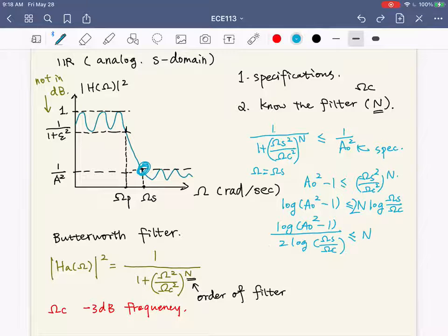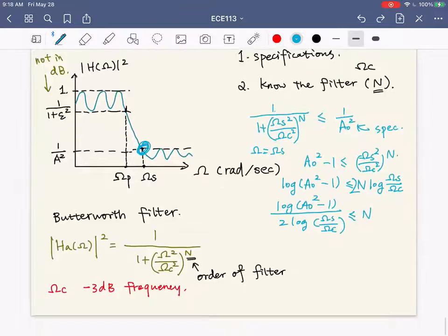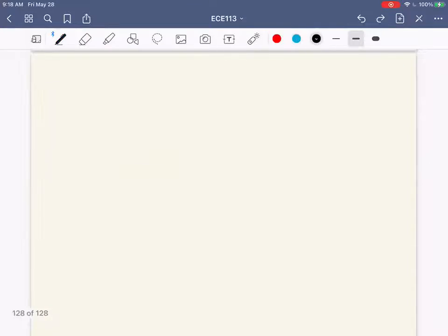So in this way, we'll be able to get our n given the other requirements. That's why we always want a bigger n if the left side is not an integer. Only when it is bigger than this value is it able to remain under the attenuation requirement, right? So you'll see that if we have a 5.8 here, we want n equals 6 rather than 5. Okay, good.